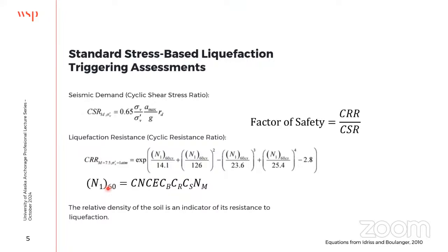So the blow counts we're doing in Japan versus the blow counts we're doing here in Alaska versus everywhere else, they're all basically the same. And so you're looking from one log to another, N160 to N160, you should have kind of a good sense for what's going on.